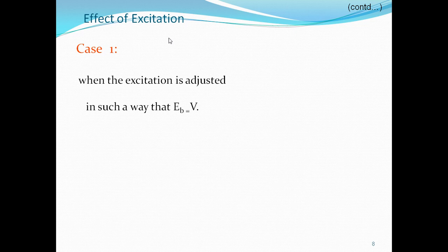But current changes and power factor changes, such that the product I into cos phi is always constant. That means both change inversely proportionally. If current increases, power factor decreases. If power factor increases, current decreases. That means a change in power factor causes a change in current.